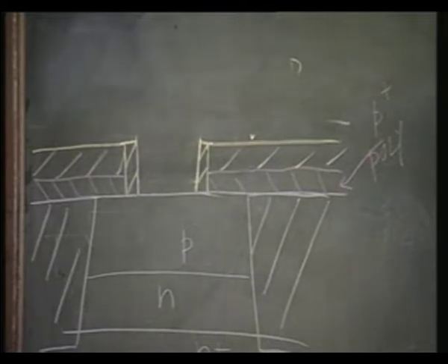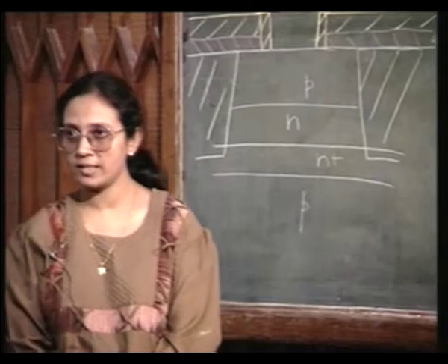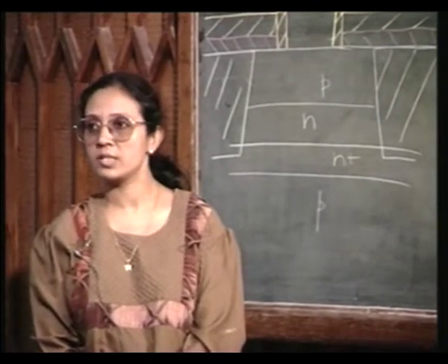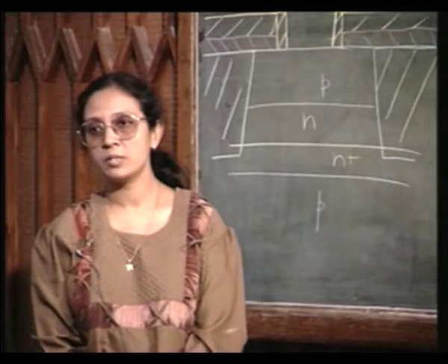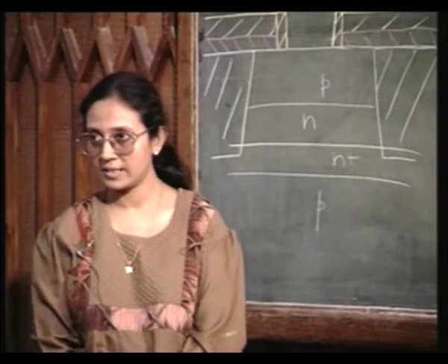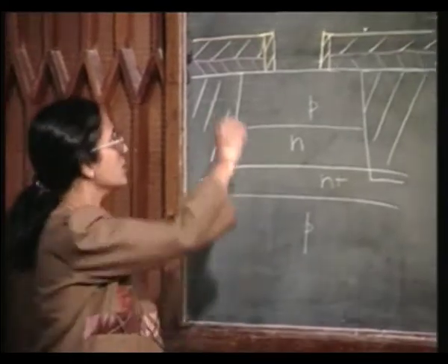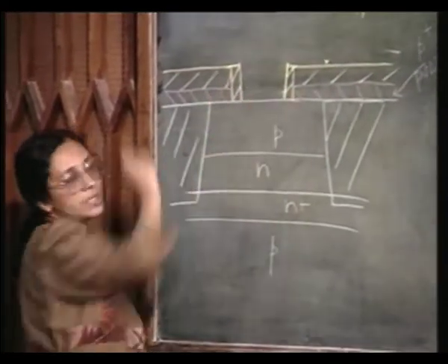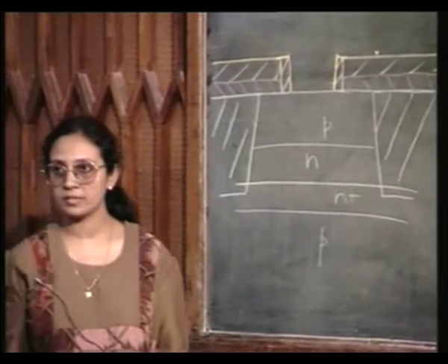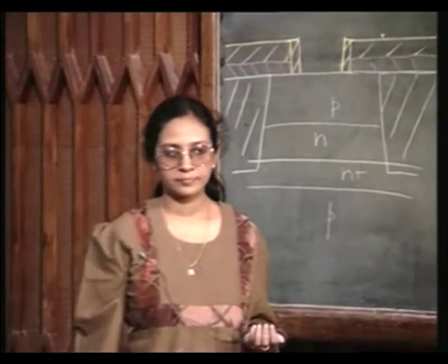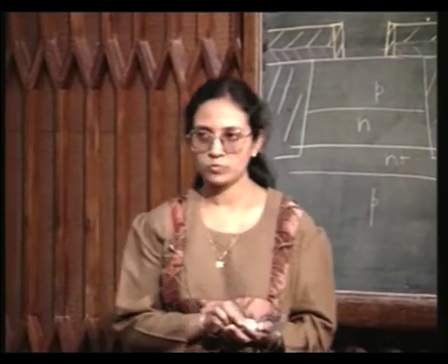In a way analogous to my self aligned I square L design, I have retained the sidewall of CVD SiO2 and removed it from everywhere else. That is, the second layer of CVD SiO2 is retained only at the sidewalls and removed from everywhere else. Agreed? Okay?